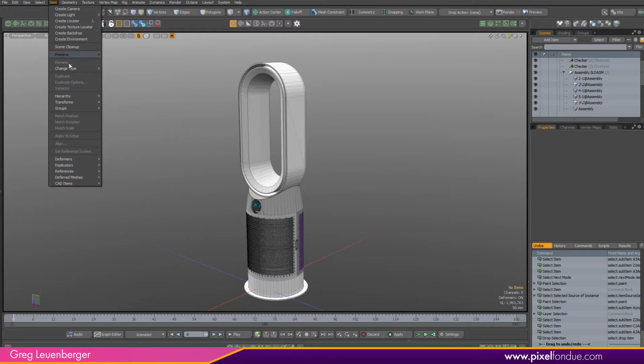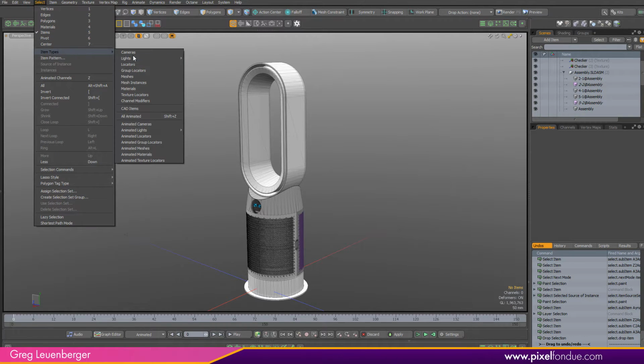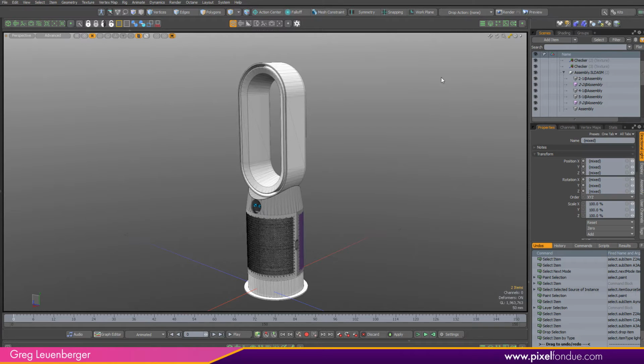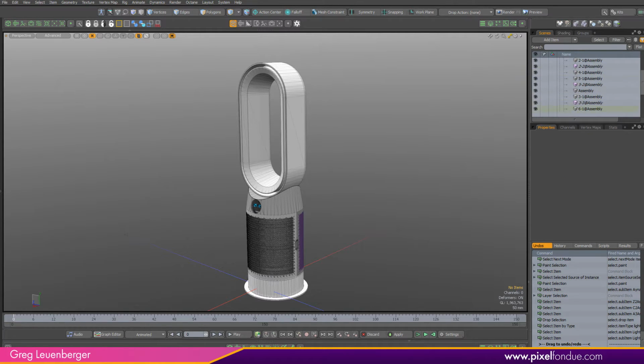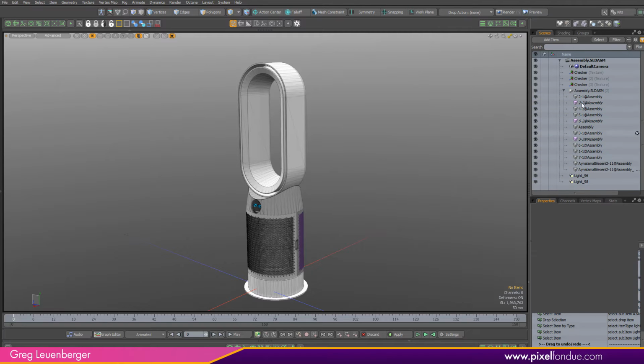We can go over here and say select all, or under select, say select by item type. So I can say lights, and it's going to select all lights. Here we just selected these two lights in the scene. If you look at the command, it's select item type, light, and super: true. We can adjust this a little bit to get just our static meshes, which are called tri-surfs internally.